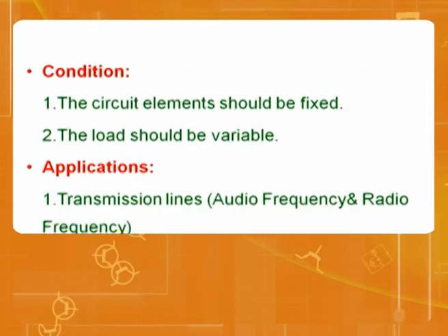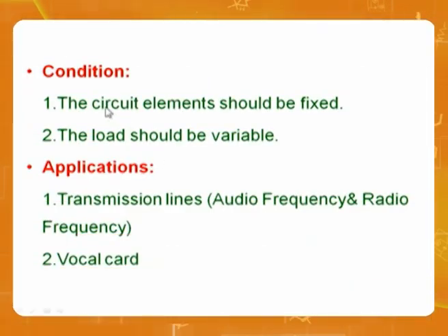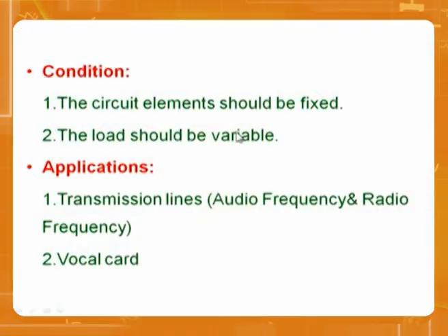I'll give some examples. Look at the conditions. The circuit elements should be fixed. For example, if the circuit elements are changing every time, better apply mesh or nodal. You don't need to go for Thevenin's and waste your time, because all that we try to do will become useful only for that one case, and next time again we have to do it. That is the very purpose of the theorem: the circuit is fixed. If the circuit is variable, go for mesh and nodal. Secondly, the load should be variable.